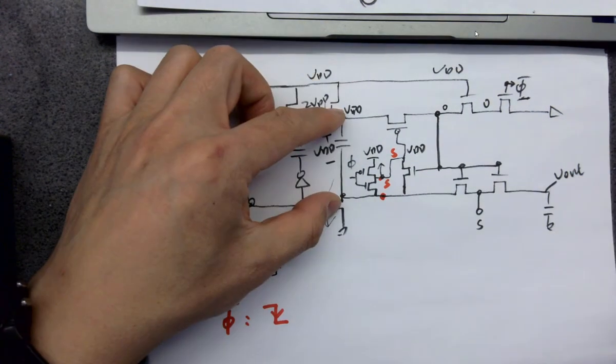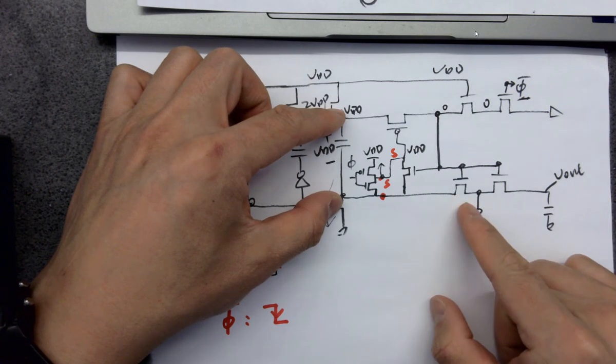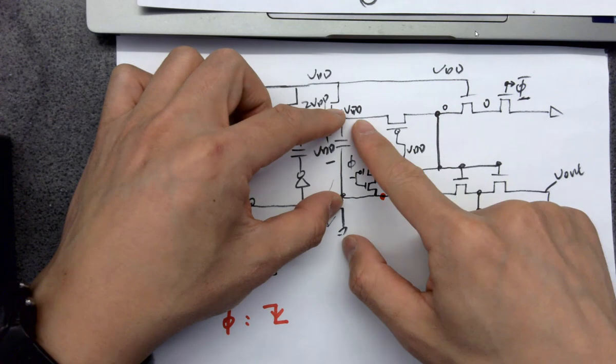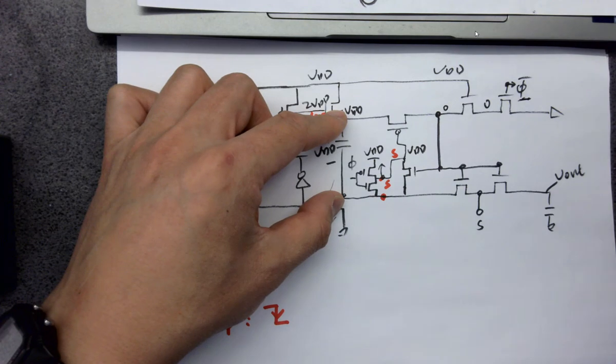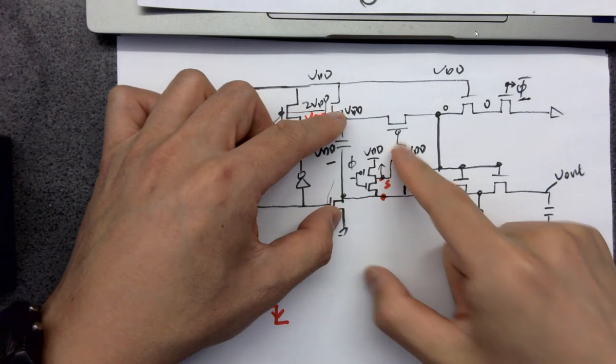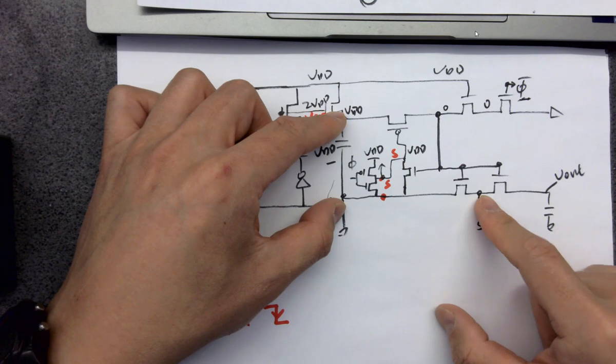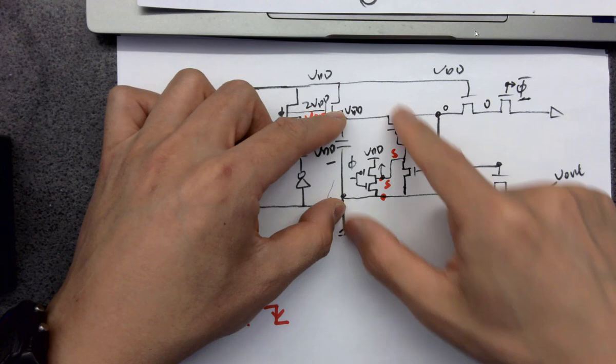Previously, I got a VDD stored over here. And because the signal is usually smaller than VDD, because you have some ADC, the maximum voltage is VDD, and you are not trying to sample voltage at VDD plus 1 volt, right? So usually all the signals have to be within the range of 0 to VDD. So the signal has to be smaller than VDD. So eventually, this PMOS is on, and this S is able to pass, because all these gates are on as well.